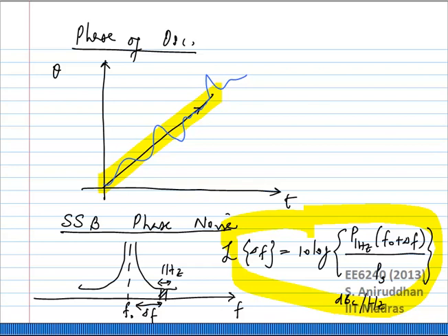In other words, if the signal really had an in-phase and quadrature component, you would split the noise also into in-phase and quadrature components and find out the individual noise to signal ratios. That is what you will have to do. But in reality, this is much more convenient and much more relevant for an LO signal, because you are really interested in the zero crossings and you are interested in the phase.